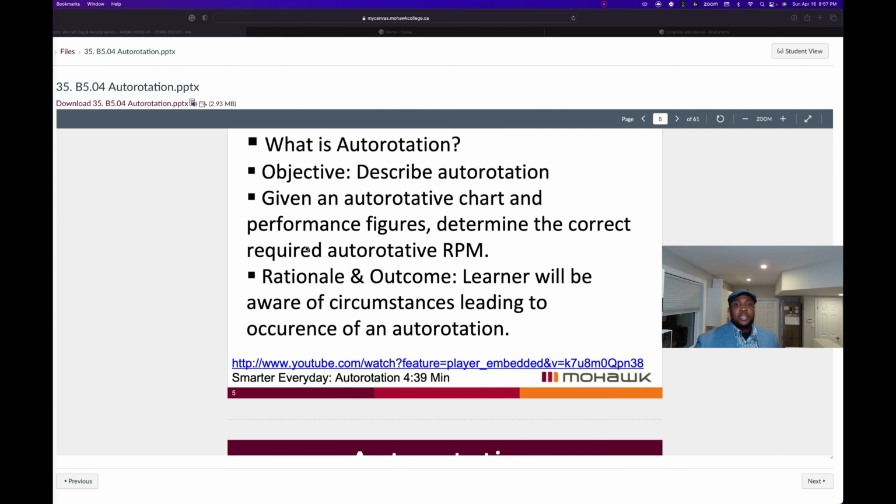During autorotation, this section is a drag force that tends to slow the rotation of the rotor. So it doesn't provide us any advantages. In fact, it is a liability during autorotation. The driving region, however, is the region that covers approximately 45%, but this 45% starts from the innermost 25% to about 70% of the rotor disc.